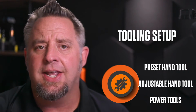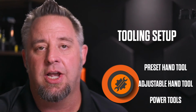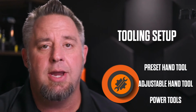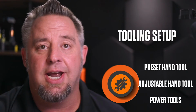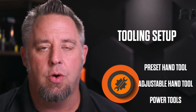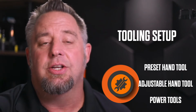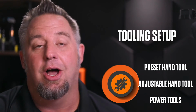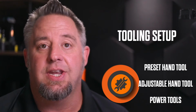One thing that can be somewhat confusing at times, we get this question: I've set my tool up on my torque analyzer. How do I know I'm getting that same value on my application? And the answer is you may be getting very close to that. It all depends on the joint characteristics between the torque analyzer, rundown adapter, or a joint simulator compared to your actual part. So it's good to know exactly what's happening on your application with a transducer, and also set that up on a torque analyzer and understand the correlation between the two, so you can be as accurate as possible. And that's how we would work during the tool setup process with measuring the torque.